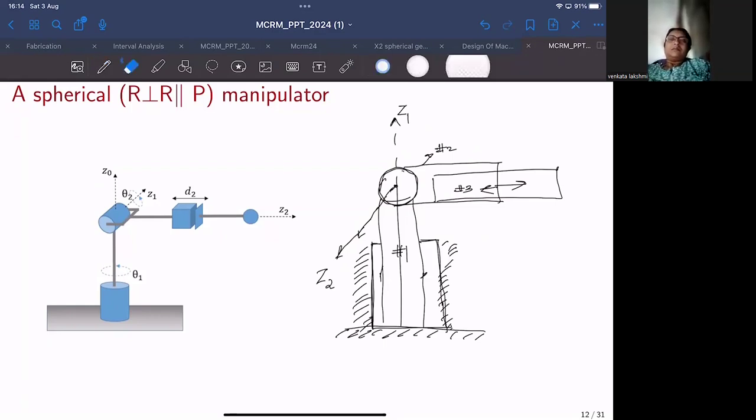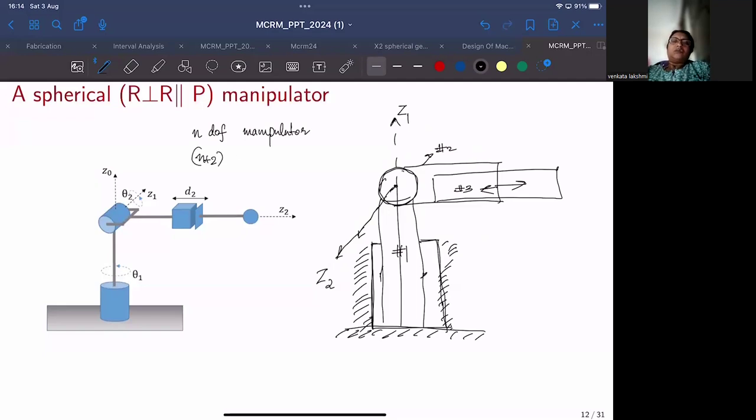And in essence, as per the formula for an n-DOF manipulator, the general rule of thumb would be to have n plus 2 frames. But it's also possible to model it with fewer frames, as I can show.